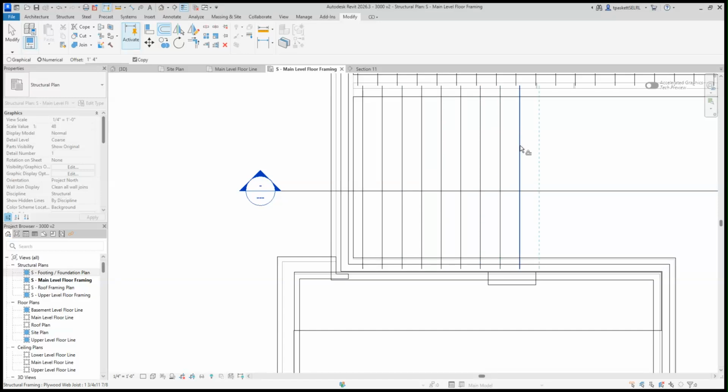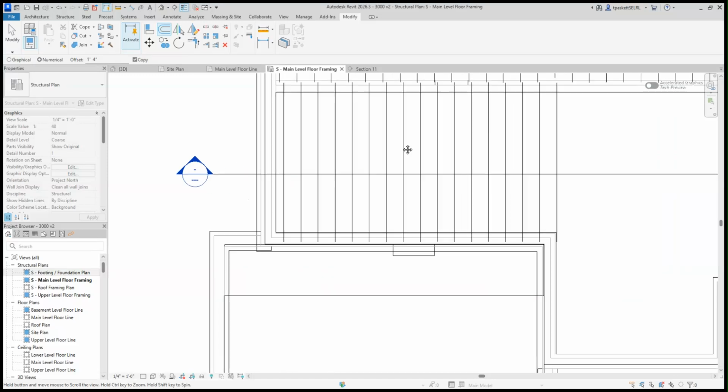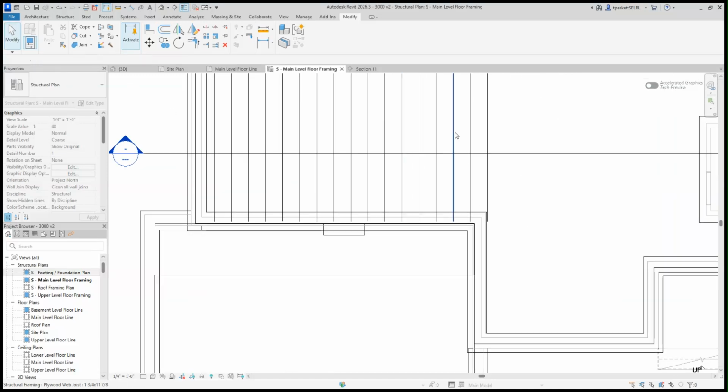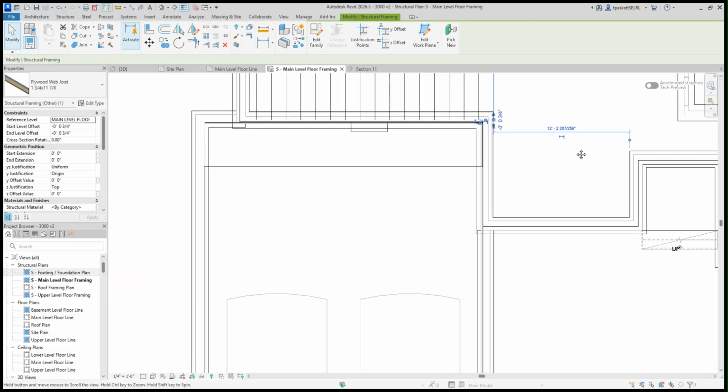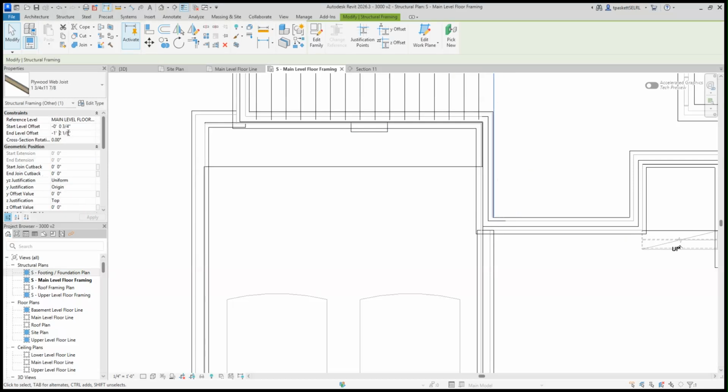There is a really strong probability that it's going to chime on me before I get to my end point, because that's just what happens. I get going. All right, this one is now off the bearing wall, so that needs to be lengthened. So then modify this by taking the blue circle and stretching it down. Now I've adjusted it by stretching it, and as soon as you do that, it's going to change its angle. And so come back in and re-level it so that you have a level floor joist.